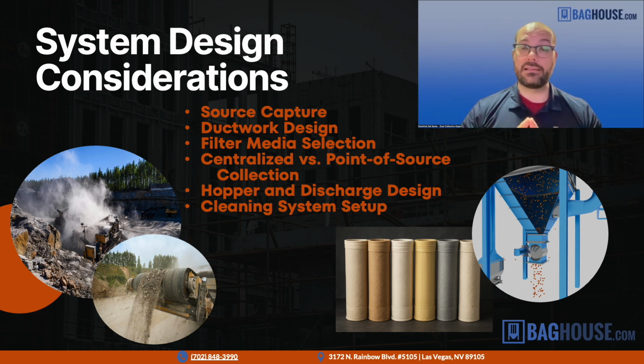And then finally, one last thing that we often see when we do inspections is the cleaning system setup. Most, if not all, modern dust collectors in these applications are going to be pulse jet style, where they pulse the filters with compressed air. Many times we find plants where they have it set on cleaning just on timer mode. So just clean the filters every 30, 60 seconds, all day, every day.